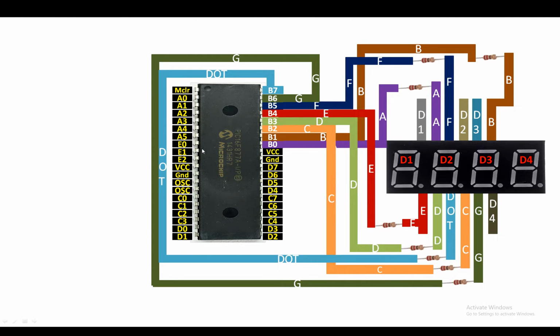If you make a manual sequence, then you have to write a manual library. You cannot use the MikroC tool. So I suggest you follow this sequence. You can use other ports like B, C, D, but this must be the same: 0 for A, 1 for B, 2 for C, 3 for D, etc.